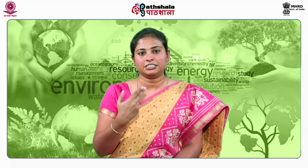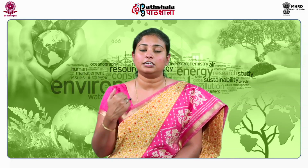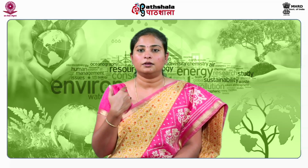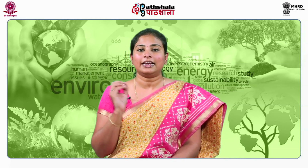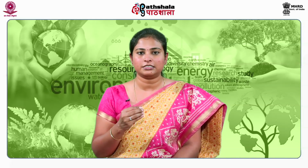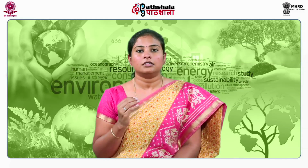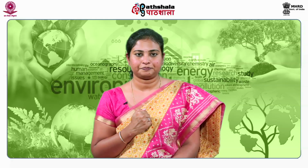In addition to preventing the leachate from escaping through the sides of the landfill, the cover also protects against disease vectors, fire, odor, blowing litter, scavenging and contamination of the environment. Now, agricultural waste, sludge, worn out geotextiles and compost are alternatives that can be used as covering material. They will also degrade along with the waste material.